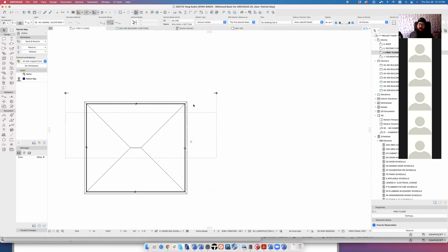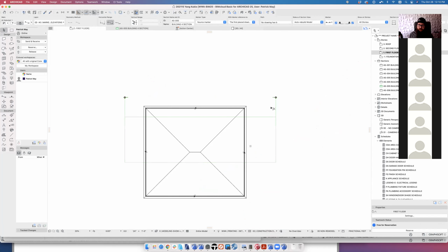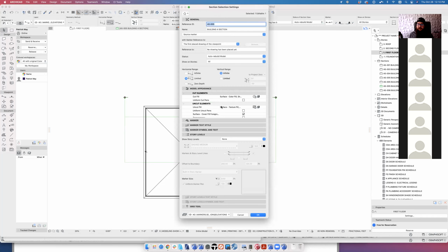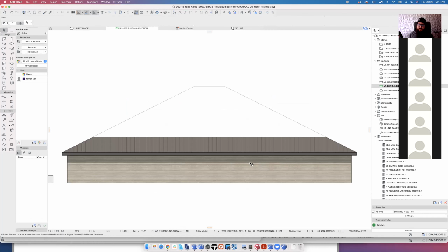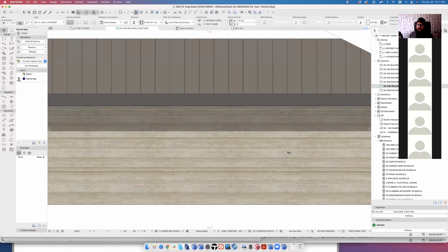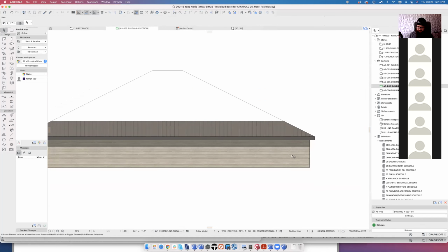One thing I'm not sure if it's going to get put to use, but I think it's important to note: we've been doing presentation interior elevations with textures from Twinmotion, but the section and interior elevation markers now have this additional uncut fill setting. It used to just be uniform. Basically these three right here were the settings we had. Now we have the ability to use the texture fill of that thing. And what that means, if I go to this elevation, is we can show that elevation with that actual surface image as part of it.